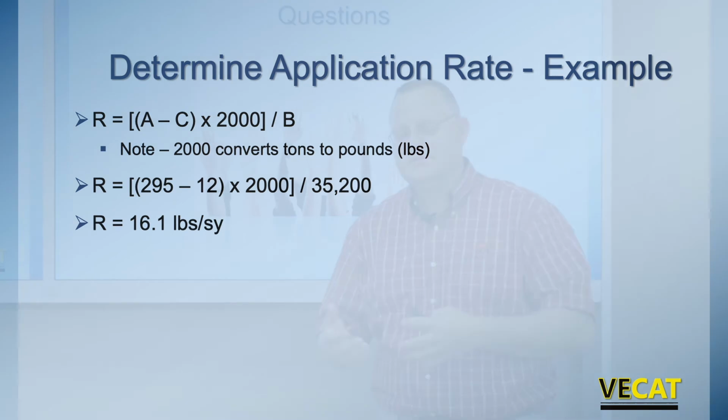We've gone through some simple math: how we calculate quantities of square yards, how many tons of aggregate are needed, how much emulsion is needed. We've looked at spray bar, distributor outputs, and speeds. So with all those things, we've confirmed how much aggregate we actually used and what our actual application rate is.